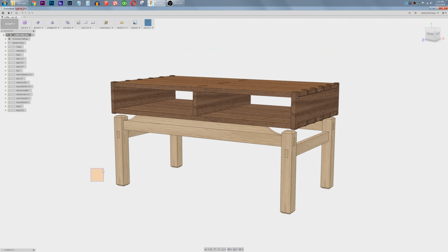However, if I go from left to right, that is a window, and a window means everything has to be 100% inside it in order for it to be selected. So this vertical divider, the center divider, is not 100% inside, so it will not be selected. And this leg is not 100% inside, so it will not be selected if I let go, as you can see right there. This face was, but not this whole component. So window versus a crossing. Most 3D modeling software uses this nowadays, but definitely use those to your advantage, and I will in this particular model.